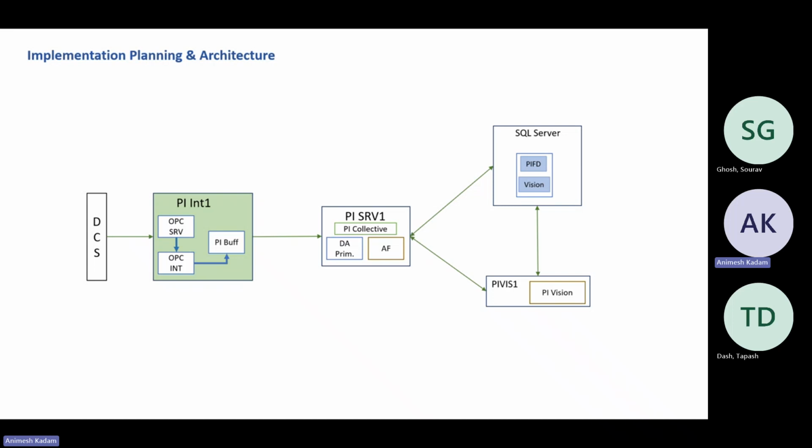It will take time to load the data in a PI Vision trend or in a DataLink report. So you really don't want that. So what we do, we just separate the AF server from the PI server, like the PI Data Archive, which I will be showing.